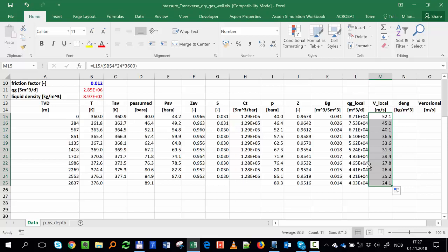So if you want to keep producing that rate, what is the solution for that tubing? Just to make it bigger, right? Choke if you want to reduce the rate. But if I want to still make the same amount of money, I have to put a bigger tubing to avoid erosion. Or I have to change the tubing every